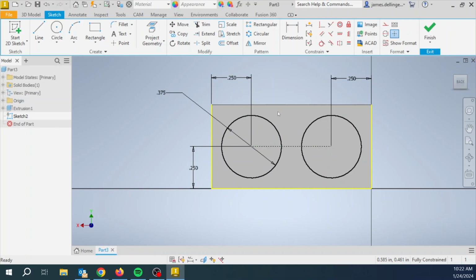Is it conceivable, if I'm doing a Lego brick, that I want these two numbers to always be the same offset? Do you ever see a Lego brick where these are not, like, do you ever see a Lego brick that's like that? No. So I want these two numbers to always be the same. So what I can do, double click it.